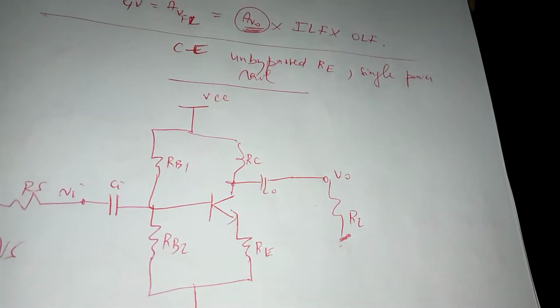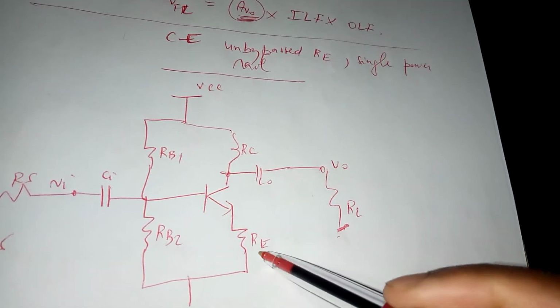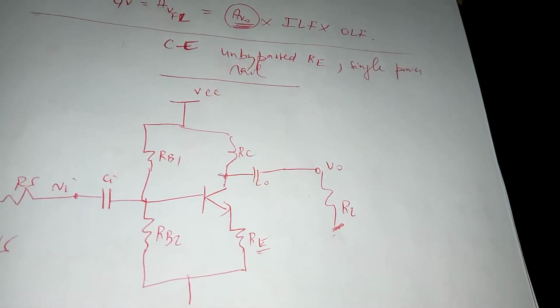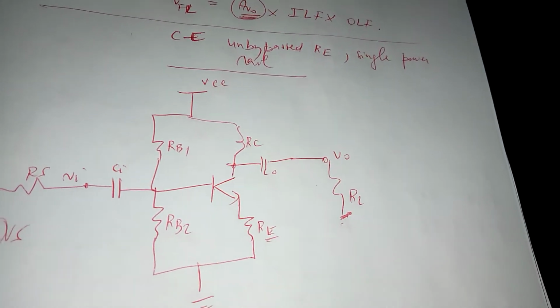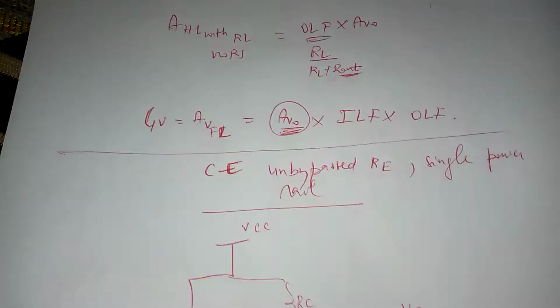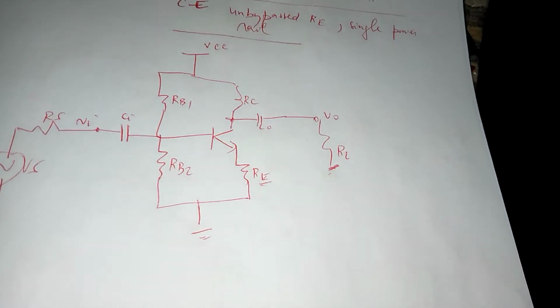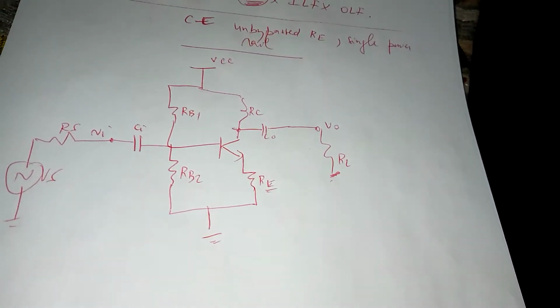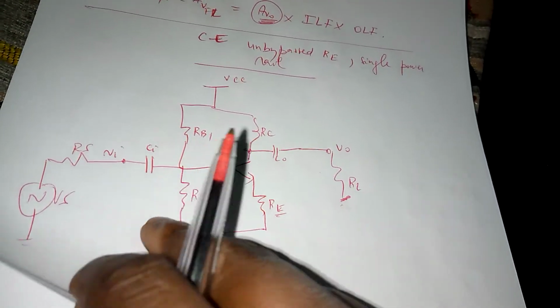DC analysis, this time I'll not go back into this. The point is that RE is not bypassed, and in fact, even in terms of AC analysis, I would like you to actually attempt it on your own before you carry on with this video, but I will provide it now. I highly encourage you to attempt it on your own because it's the same principles, knowing that a cap behaves like an open circuit in DC and a short circuit in AC. So now DC analysis, as I mentioned, we've covered.